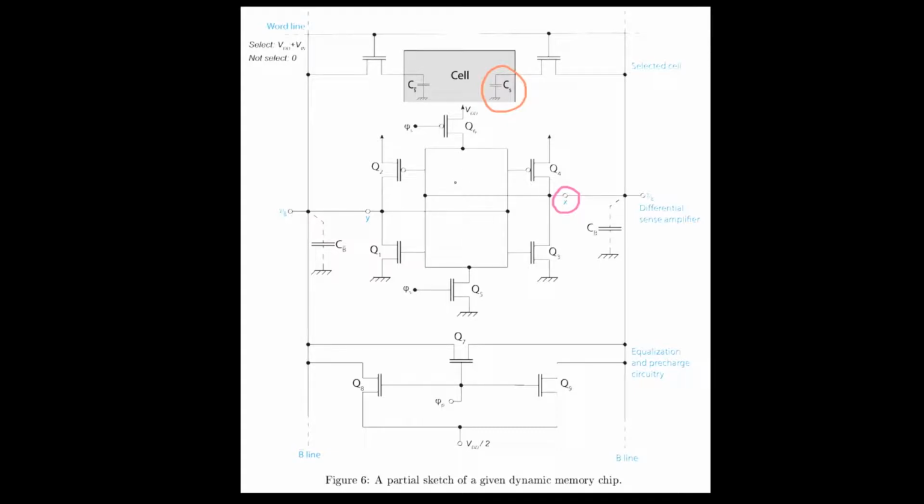This latch has its metastable point at the pre-charge voltage. So if the voltage at node X is a little bit larger than the pre-charge voltage, then the latch will ensure that the voltage at node X will be increased to the positive logical voltage value. When the voltage at node X is a little bit smaller than the pre-charge voltage, then the latch will ensure that the voltage will decrease to the lower logical voltage. And it does so with an exponential function in time. And that is actually why this latch is so preferred, because an exponential time response is a very quick response with respect to a linear or a quadratic response.